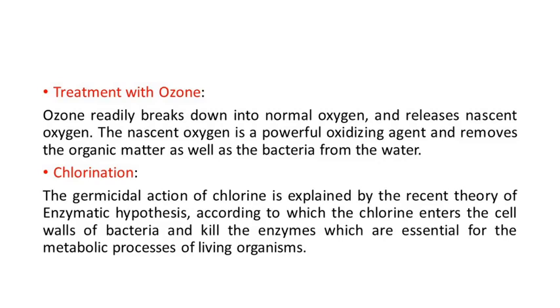So first, it stops metabolic activities, it avoids contamination of water, and it prevents the regeneration or growth of bacteria and organisms. That is the major advantage of chlorine. The residual effect of chlorine is a long-term effect, and that is the next advantage of chlorination. The residue remains for a very long time. If you add chlorine one time, the residue of the chlorine remains present for a very long time.